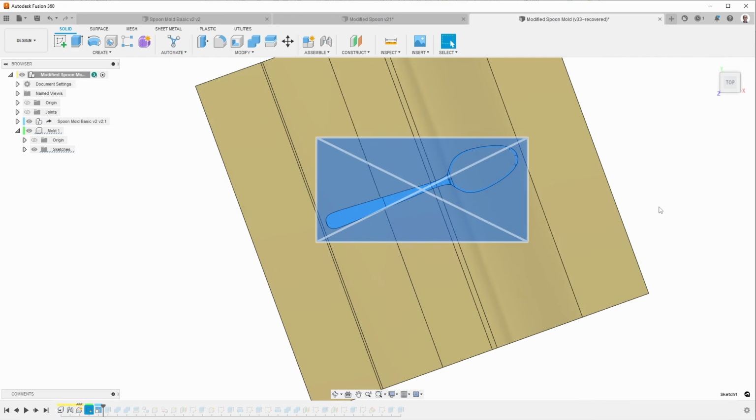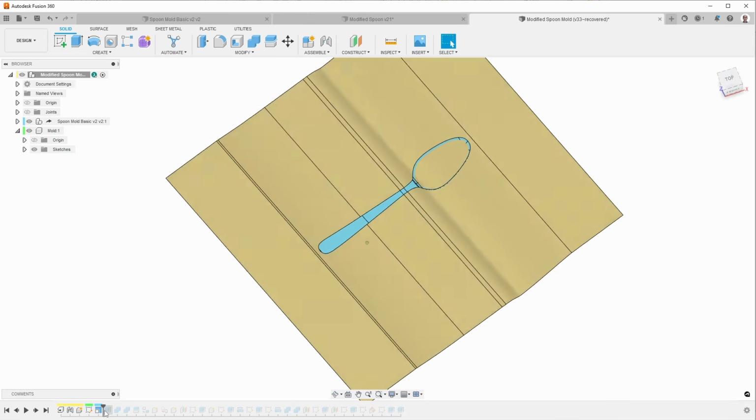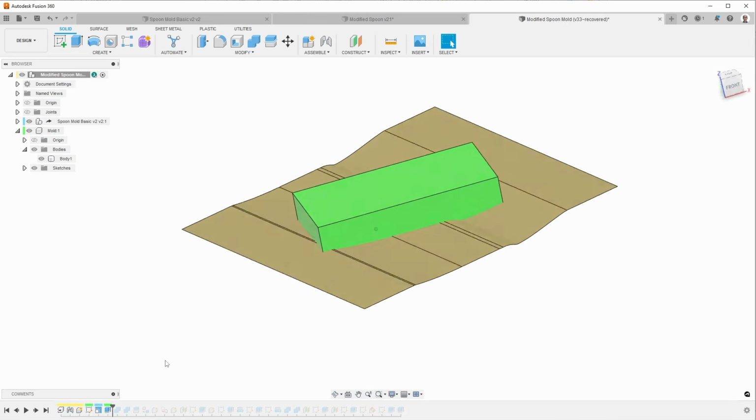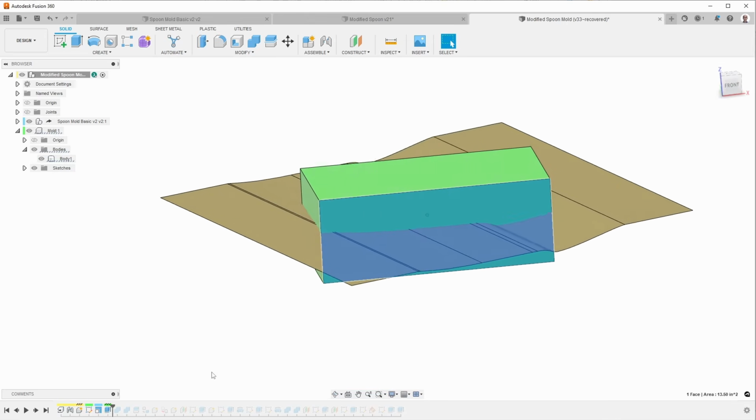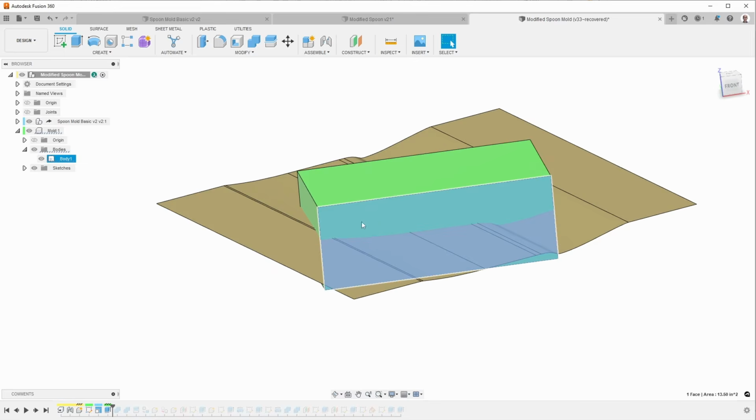If it's too tight, you could have problems keeping the mold halves together and you can get flash or you can get blowout of the mold. So I rotated this so that I could get the best margins all the way around. And then once I did that, then I could extrude the material. And this is going to be split in two pieces, the A and the B side, using this parting line.